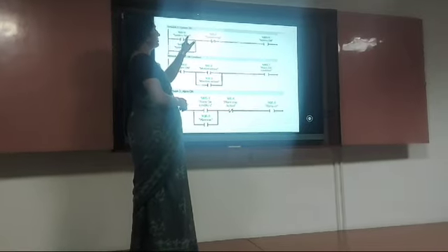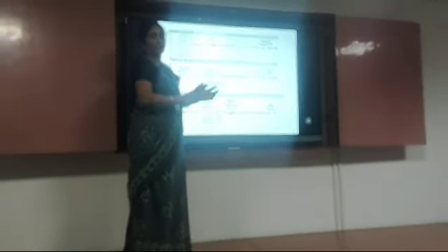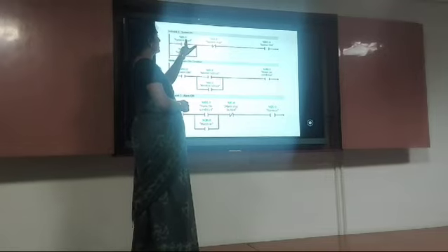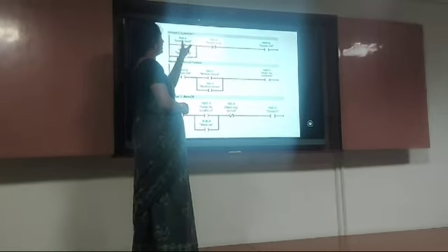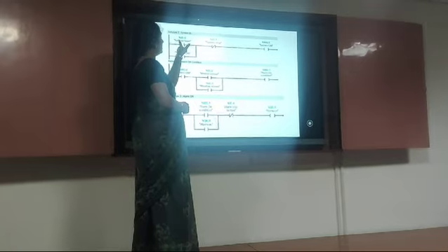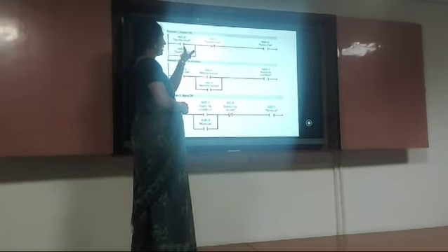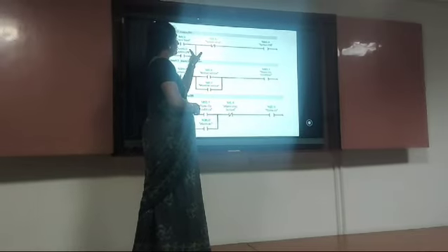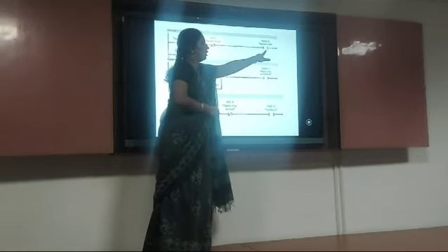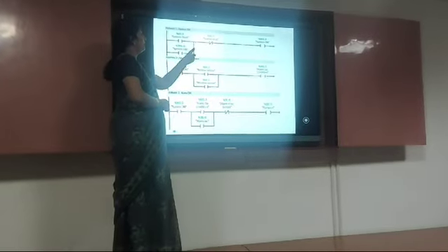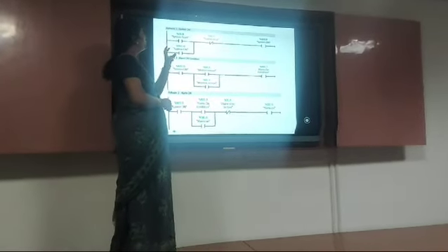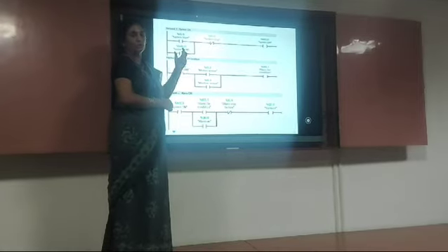So we have the system start, with which we start the burglar alarm system. When we enable this signal system start, this normally open contact is going to get closed. If it gets closed, the system on output is going to be energized. What we have done here is latch it with the input. We can have the system start as a push button also.